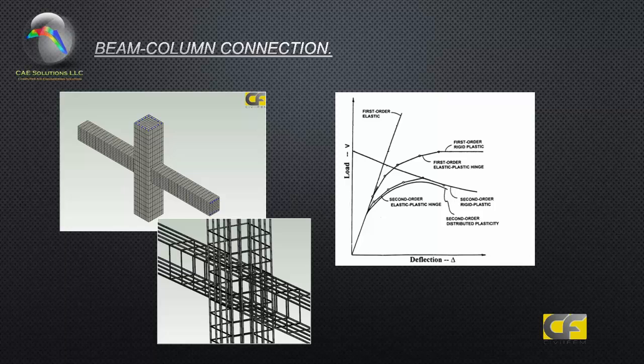other phenomena. So one of the analyses that we can perform is the linear elastic analysis, also called first order analysis. Well, we know that Hooke's law is applied. Strains or deflections are proportional to forces or stresses. And this is a common analysis that we always make in our design.